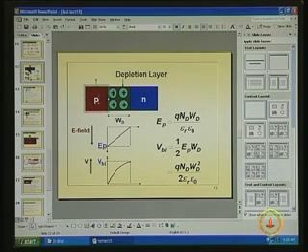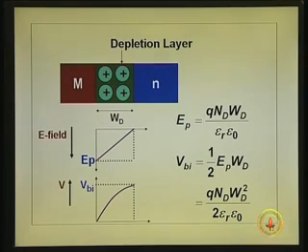Okay. This actually is metal. Let me change it up. What I was intending to say was, it is almost like a PN junction. Instead of p-type material, you have got metal there, then you have the depletion layer. The voltage across the depletion layer is equal to the built-in potential, that is VBI, okay, and that is 0.953. Now, what we are trying to see is what the depletion layer width is when the doping is very high here. So, now just like in the case of PN junction,